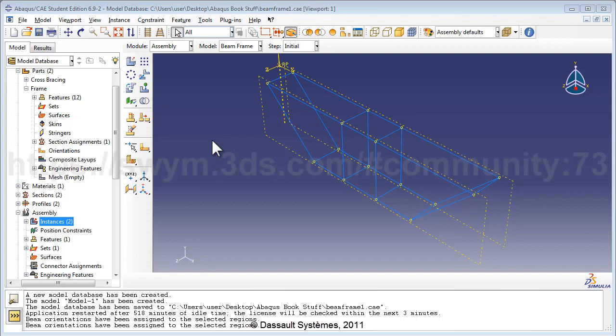between the cross brace members and the frames. But before that, let's talk about the joints in the frames themselves. When we created trusses in the truss tutorials, the nodes of the trusses were pin joints by default, because when you use truss elements in Abaqus, the nodes of the trusses are automatically treated as pin joints by Abaqus. Beam elements, on the other hand, are different, and the nodes between the beams are treated as welds. In a weld, the nodes are basically fused together, so you're going to see transfer of both displacements as well as moments, whereas in a pin joint, there's going to be no transfer of moments.